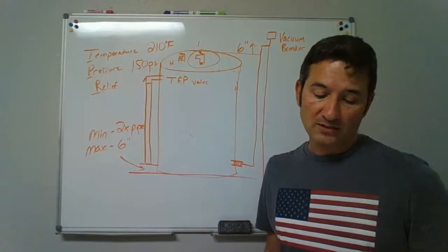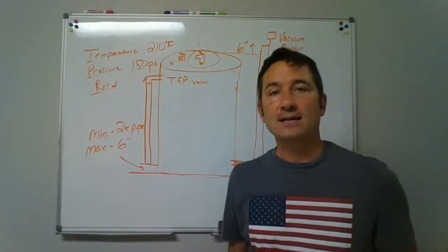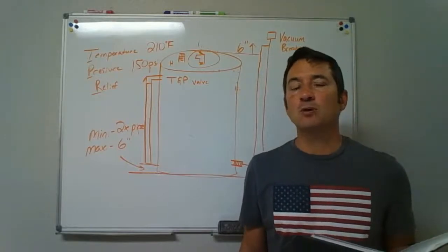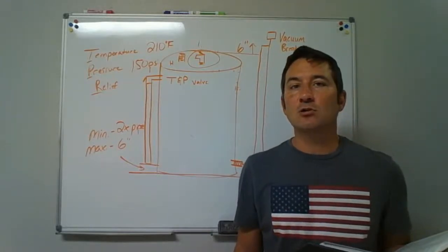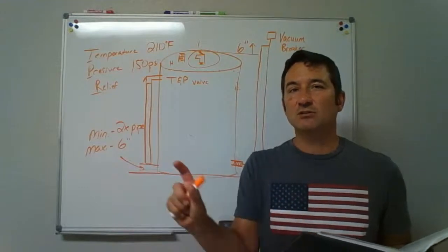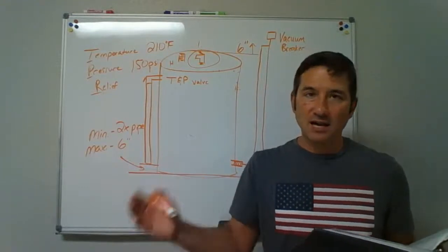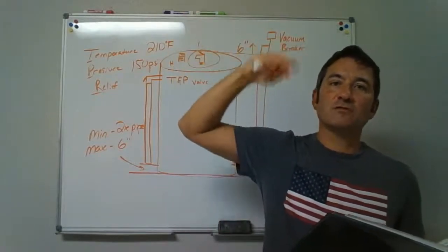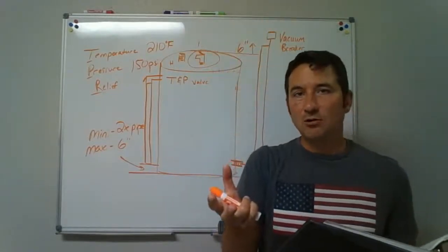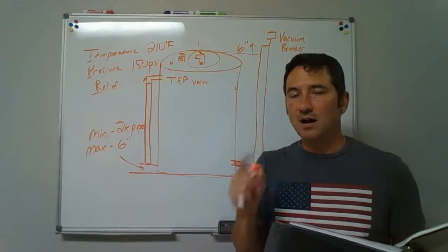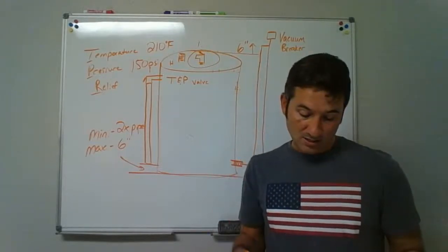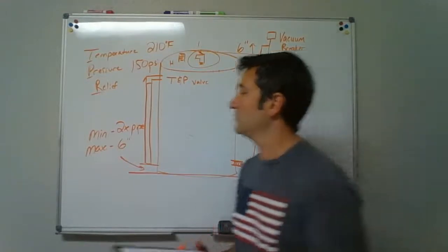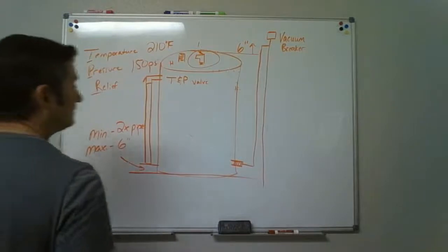Unventilated crawl spaces. If we put one in a crawl space of a Habitat home, they've been doing unventilated crawl spaces. They've been insulating the exterior walls, no vents in there, lining plastic from the floor and leaving the insulation between the floors out, conditioning that crawl space. Well, that's an unventilated crawl space. We have to pan that water heater. Okay. So if this was in the crawl space, what we did